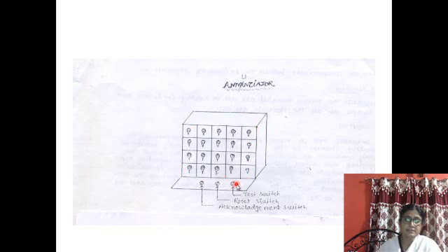By pressing the test switch, all the lamps should glow. If a lamp is faulty, then that particular lamp may not glow during a failure. So in order to check the healthy condition of the device itself, the test switch is there. By pressing it, all the lamps and the hooter can be checked.